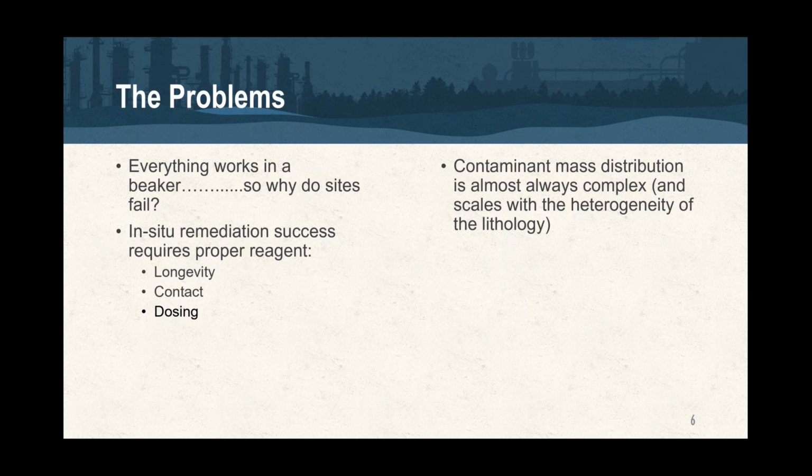What's really important is that, as the lithology changes, you have soil samples that span those varying geologies. A lot of times the mass contribution in the sorbed phase is underestimated, and that's just a quantity issue. A lot of the data that we review is usually thin and old. Some samples are 20 years old, and we really can't use that for current remedial designs.